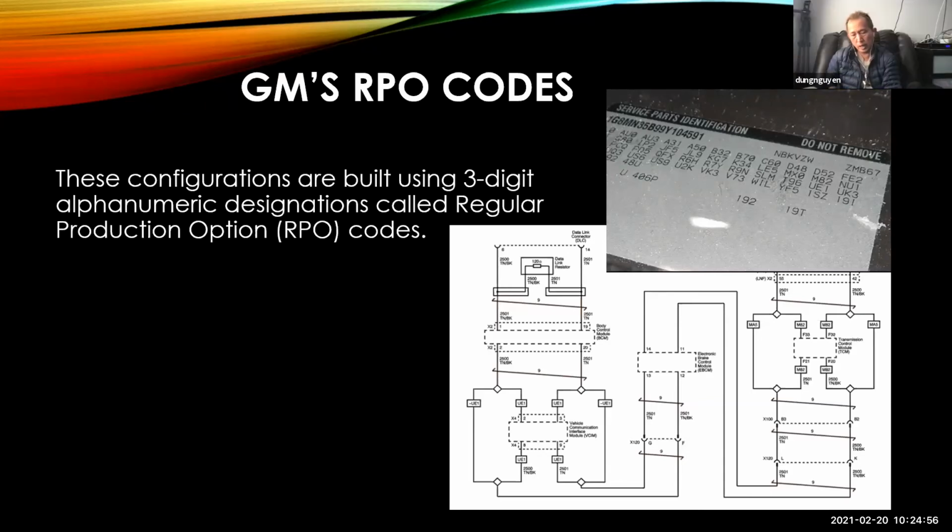So how did the vehicle run with the gateway module gone bad? Okay. So it depends on where the gateway module is and who's using it. It seems like the central universal connection that links everyone together, but does my powertrain module know how to control the engine? Maybe. Does he really need to talk to anybody else, or can he just operate the engine and go, you know what, I don't know these things, so I'm going to use these sensors as higher priority and make the best choices I can.